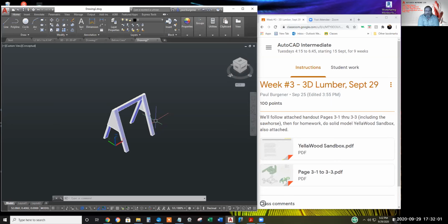I believe you're thinking an AutoCAD unit represents a foot. Yes, you hit it on the head. Now I can change it to an AutoCAD unit equals a foot by scaling this by 1/12. Okay, and then instead of being 3.5, it'll be roughly a quarter of a foot. All right, you answered it.